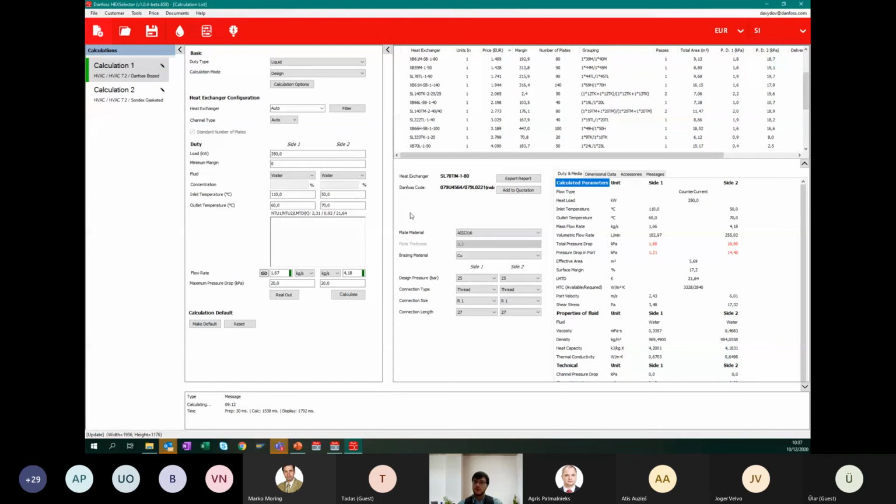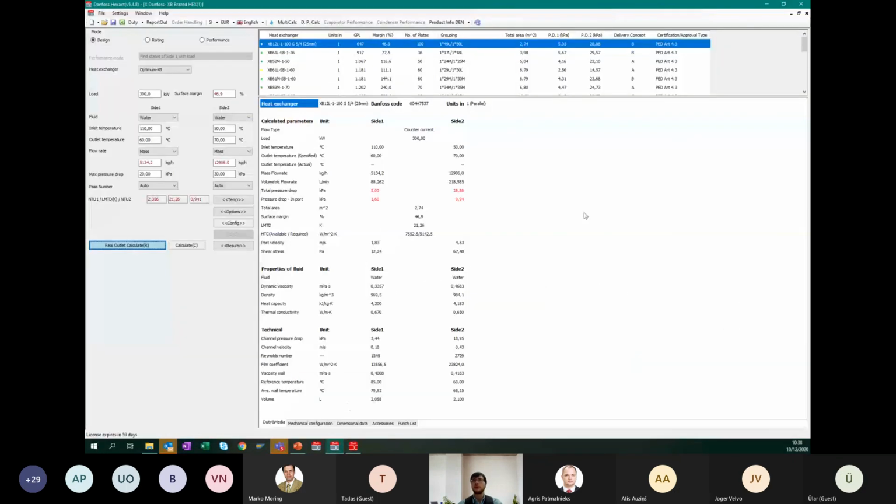Okay. There's one question. If you optimize a heat exchanger pressure drop to reduce heat exchanger price, how much does this influence power consumption of the pump over the lifetime? I don't have a real price calculation for you right now, but considering the first step optimization I made was just 2 kilopascal, which was 10% of the available pressure drop, that impact is close to unmeasurable.